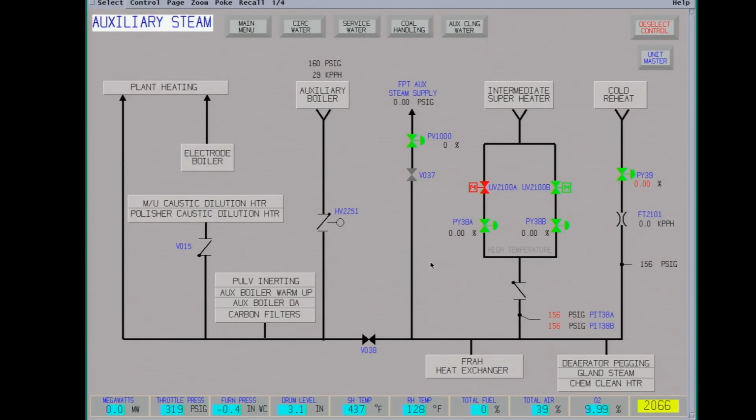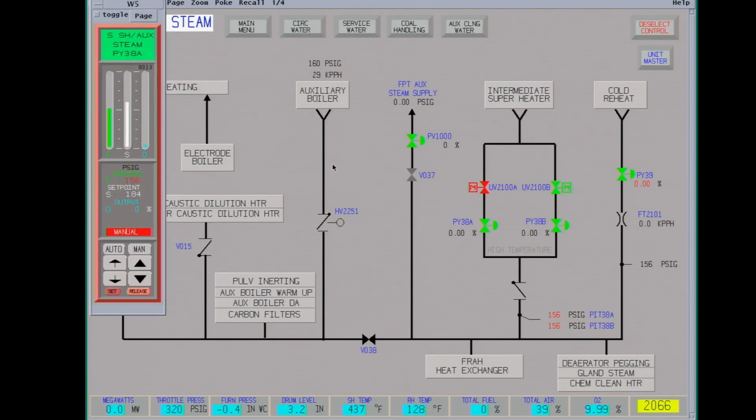Big thing, you always want to keep steam on a turbine if the steam seals are on. If you lose your sealing steam, you need to kill the vacuum on it. You don't want to pull cold air across the shaft. It can cause problems cracking and rubbing on the seals. We're going to open this up just a little bit to start warming up. You'll have to call the guy to run the aux boiler just to let him know, because he's going to start dropping flow on it. A lot of these valves have to move quite a bit before they open. They're driven closed.